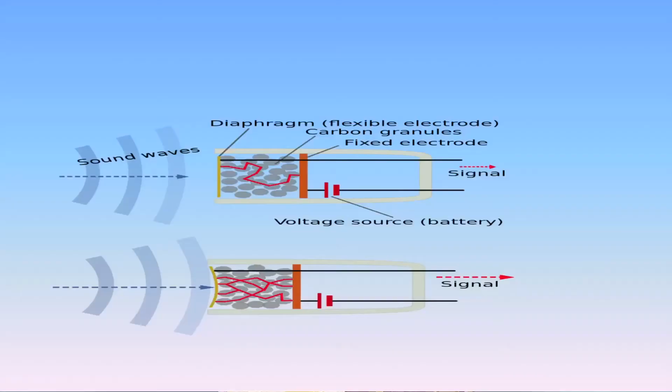It includes a diaphragm. In the old phones, the diaphragm was made up of two metallic sheets between which carbon granules were filled. As one speaks, the diaphragm gets pressed following the same pattern as the sound of the speaker. In turn, the carbon granules also get compressed and decompressed, coming closer and moving away, thus increasing and decreasing the conductivity. A current is sent through the diaphragm.